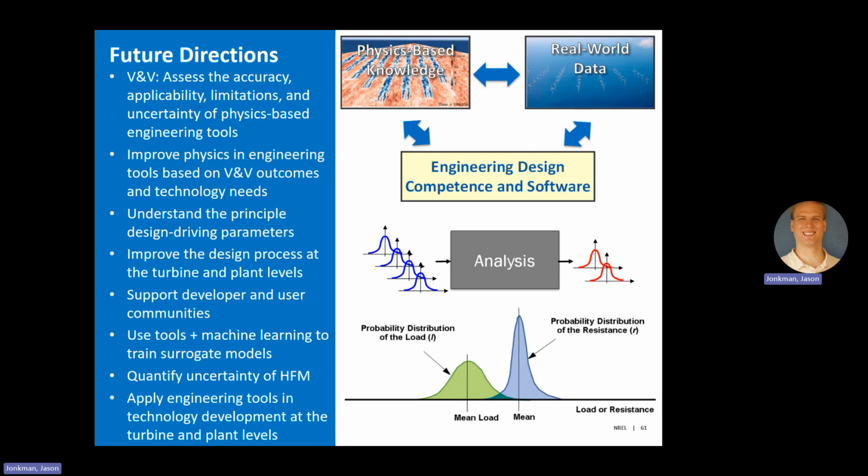The other approach is to say, well, OpenFAST runs great, but if I'm doing an optimization, say with FLORIS, that's steady state, I still want to at least estimate what the loads are. So we use tools like OpenFAST and FastFarm to generate surrogates that can be used in lower fidelity tools. So those are where we're looking at AI/ML type approaches.